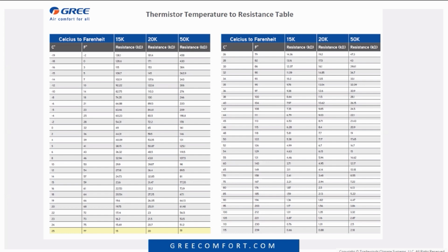Anyway, so again, those rules don't change. One other thing I will share with you: if you don't want to unplug thermistors and you want to see if they're reading properly or not, in the GMV6 service manual we have the voltage drops. So you can take your meter on DC volts with needle point probes and put the probes right on the two wires going to that thermistor, and it gives you the voltage drop. And it also gives you the chart. At that voltage drop, it's reading this temperature.